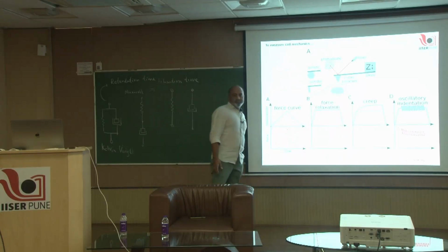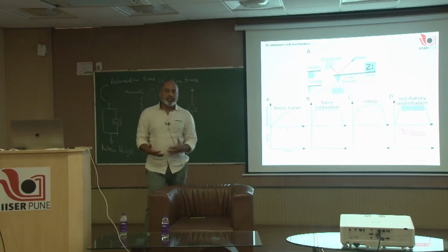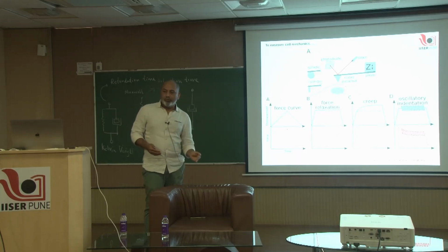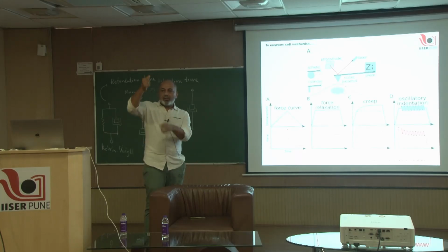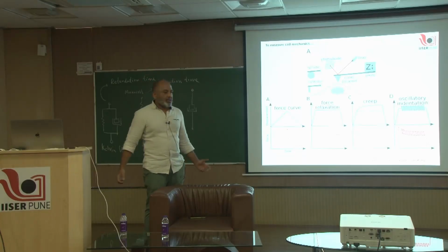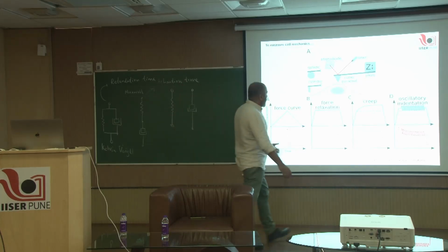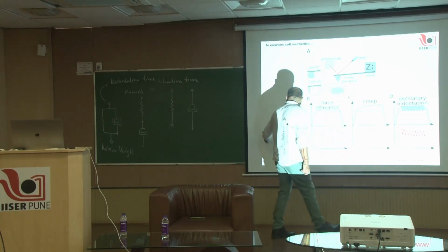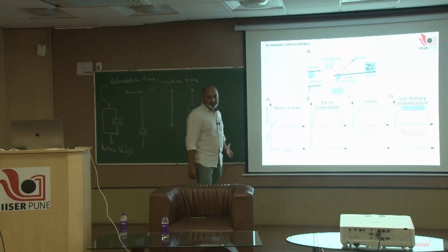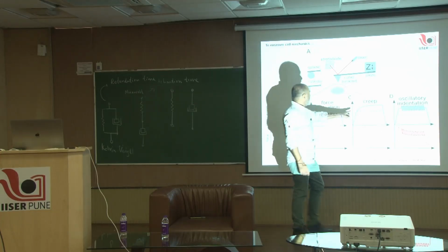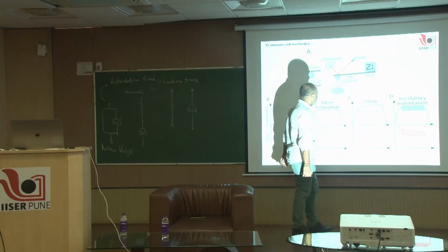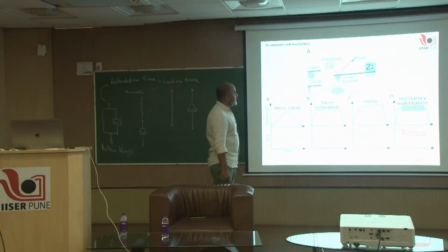The third one is that, in a feedback loop, you hold the stress constant, and that is called creep. The material keeps elongating under a constant force, like when you attach a weight and it is slowly going down, and that is called creep, and then it finally stops going down any further. That can be done with AFM by applying force feedback, which is the clamp experiment that Sabyasachi used. You have a constant force on the material, and this generates a creep, and the time required to fully elongate is the third one.